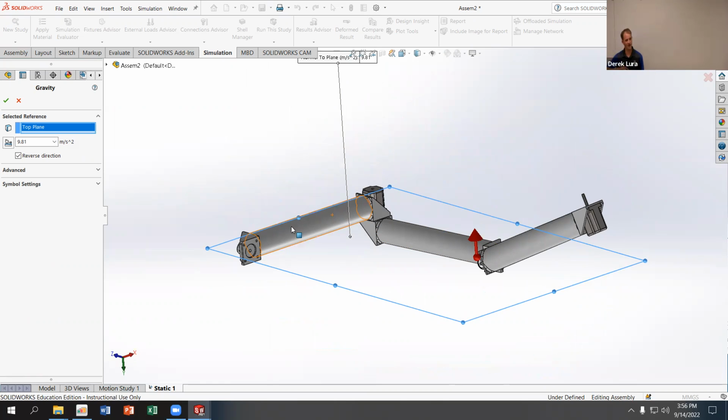So if I put all of my arms going in one direction, so there's the largest possible distance, and then I have gravity going perpendicular to that length, that's going to be the most load. So I'm going to go ahead and keep the gravity going in this Y direction. So going actually in the negative Y direction. It's using Earth gravity 9.81, which makes sense.